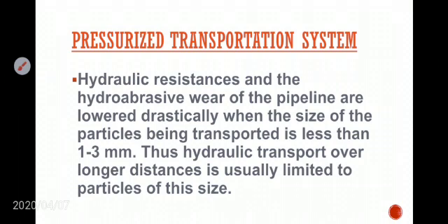So generally, in order to achieve successful transportation by this pressurized transportation system, we need to break up the mineral size to 1 to 3 mm. Thus, the hydraulic transport over longer distances is usually limited to particles of this size. So if you want to transport the slurry or the hydraulic mixture for long distances, then definitely the mineral size should be 1 to 3 mm only.